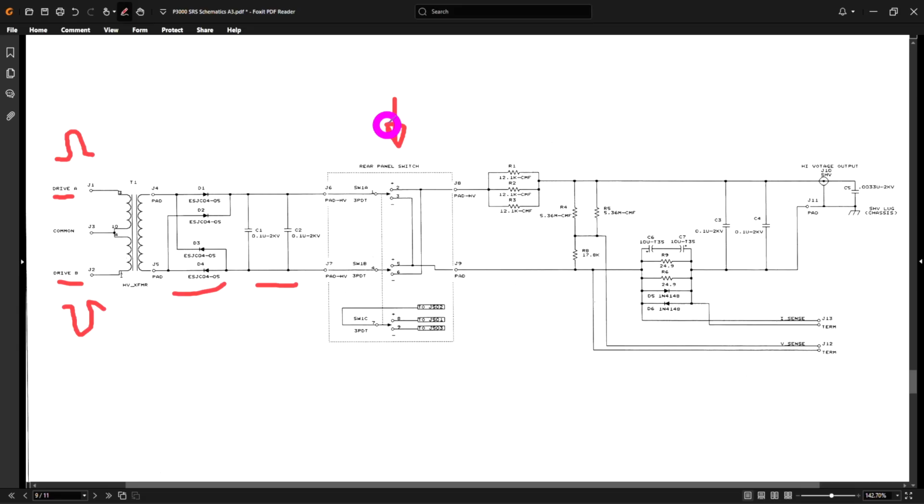You have to manually switch it, and it's really important that when it's running you don't switch it while it's active, because all these capacitors on the output side are all charged, and if you swap this, you mechanically take two capacitors, each let's say with 1250 volt on them, you flip them and you connect them back together. So a huge amount of current is going to flow through this and destroy everything. So they explicitly tell you to make sure you do not do that. But the rest is pretty obvious.